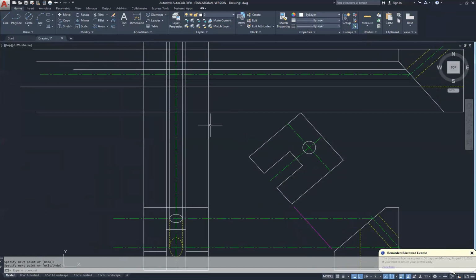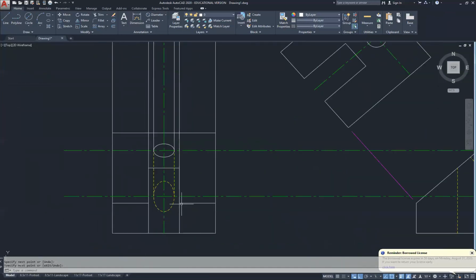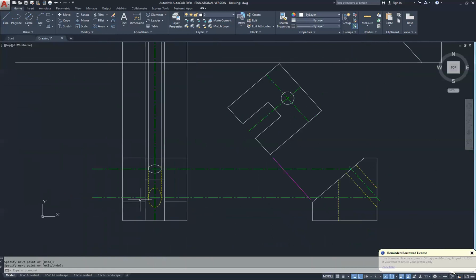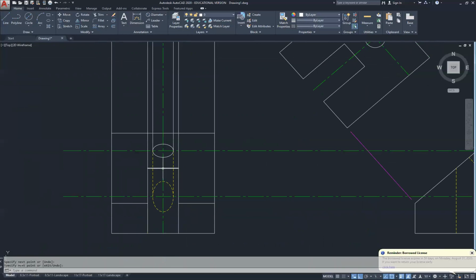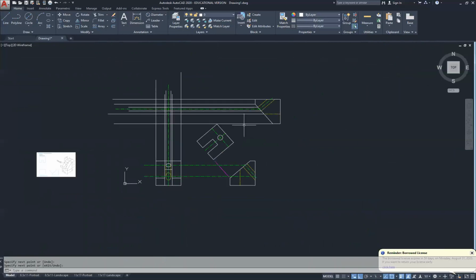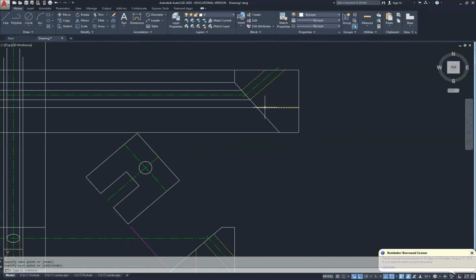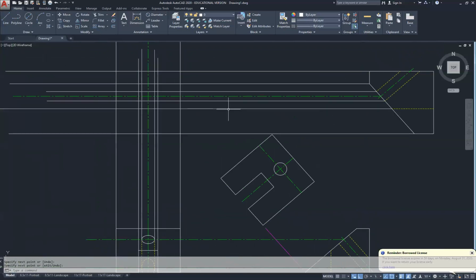Make our drawing a little bit clearer. Let's go ahead and understand where we're at. We got this piece right here in the front. That's going to have a depth until it intersects at this line right here. That line is the hidden line represented here, projected across. So I'm going to go ahead and trim. I'm going to use that line as my cutting plane. And those two sides here and here, I'm going to cut above.